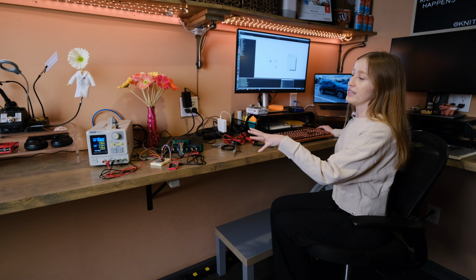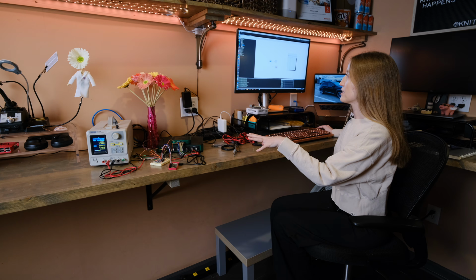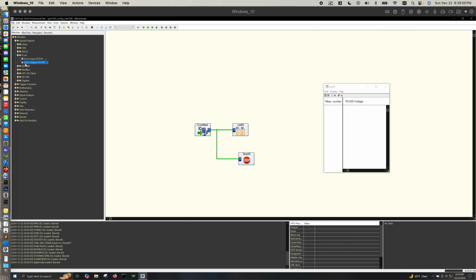To open up a socket and send SCPI commands, I do that with the ICOM input block. As you can see, depending on the driver you have, you can have a straight analog input or output. Those particular blocks are used with the MCC measurement devices.